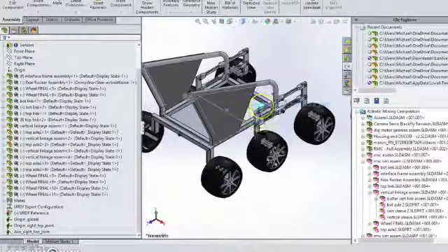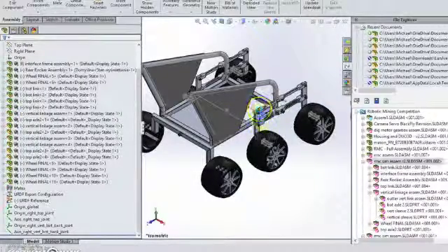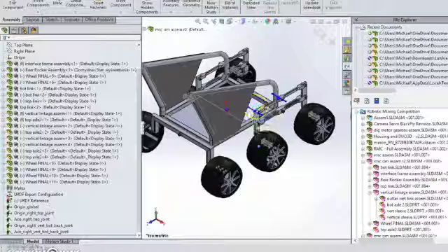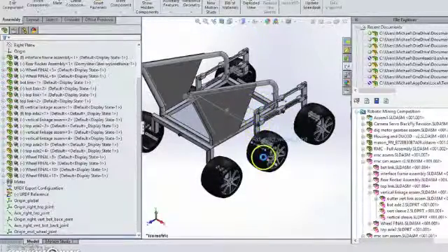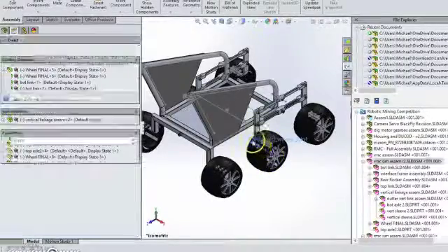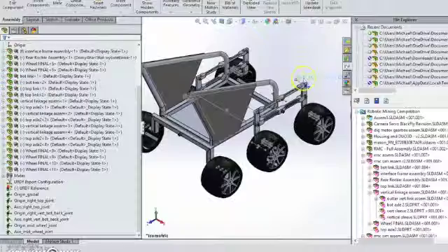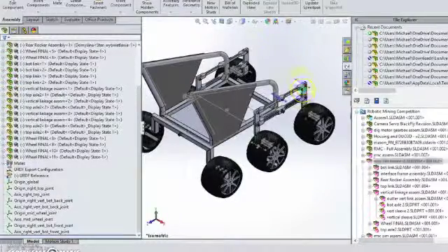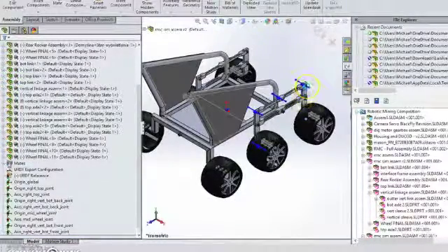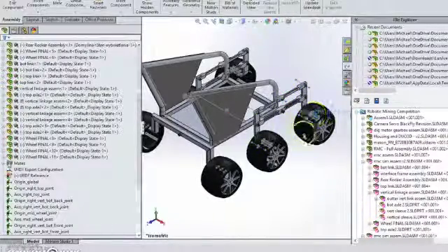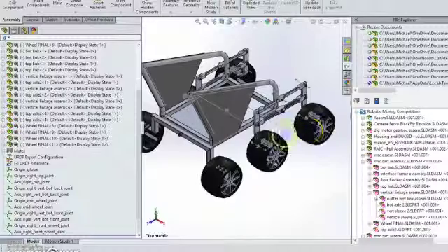Now, one thing to remember is that the revolute joint or continuous joint, as described by URDF, eliminates all but 1 degree of freedom. So the origin can be any point on this axis, and it still effectively eliminates all the degrees of freedom except for the rotation about that axis. So if the origin comes in a place that you might slightly not expect, that's not necessarily something that you need to worry about too much because it's completely acceptable.